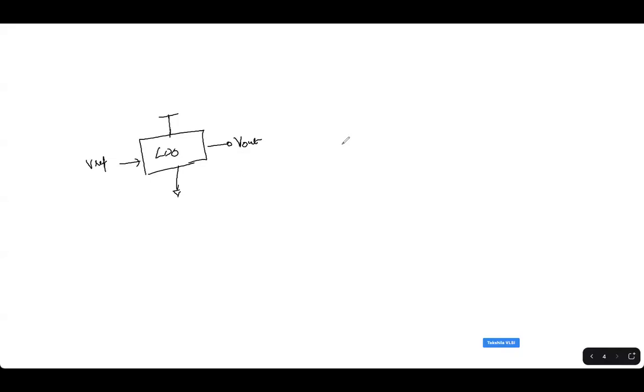It's a small signal analysis. You would like to see how much of it appears at the Vout. So in the setup, we put, let's say, a 1.8 volt DC supply, and we give AC as 1 only for the supply.